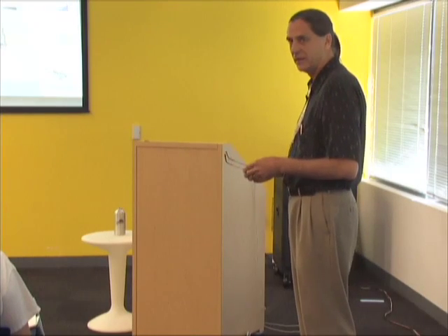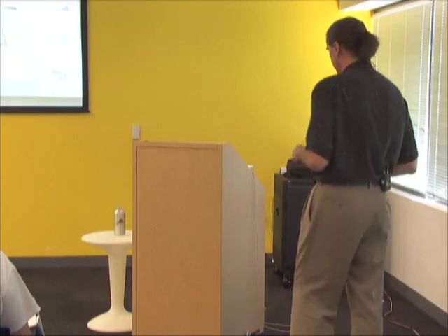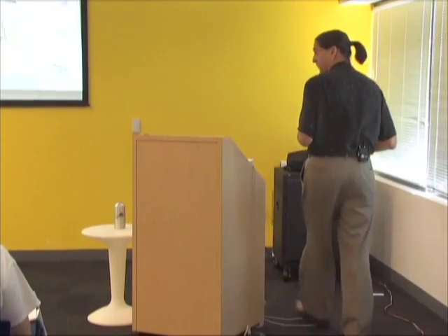You can easily get models that are 40 and 50 megabytes by putting complex textures in them, but they won't have the poly counts. And textures are actually really easy to work with. You just need to turn them off when you don't need to look at them, and then the models become easy to deal with. But these models will all not be easy to deal with, even with the surfaces on.